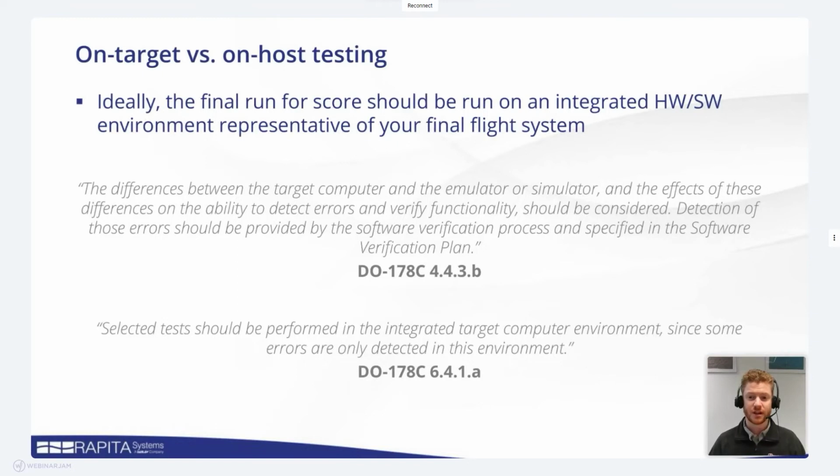On host versus on target is another hot topic. The older standard, DO-178B, was much less specific about this. As things have gone on, and on-target development tools, on-target code coverage tools, have improved, the authorities are pushing more and more to doing your testing on target.